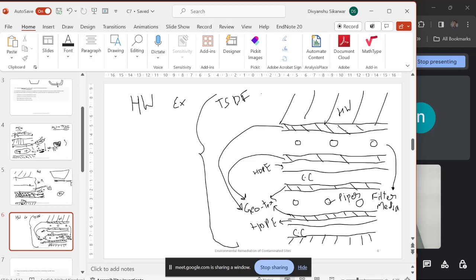Yes, we can say that, but the main reason, if we think, is that the soil particles and hazardous waste which is present here don't clog this filter media, right? If it is in direct contact, those particles will also come here. The sludge also will come here, and it will clog this filter media. It will be under a lot of waste, right? So we can't just dig again and again and unclog the filter media, right? Yes, sir.